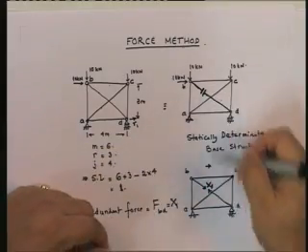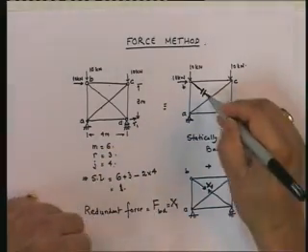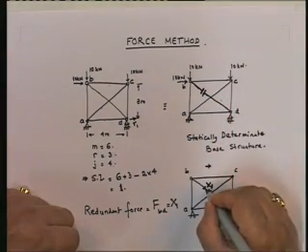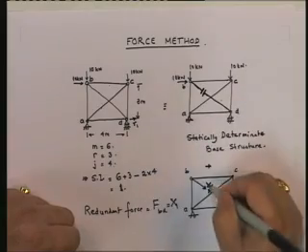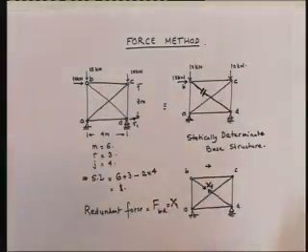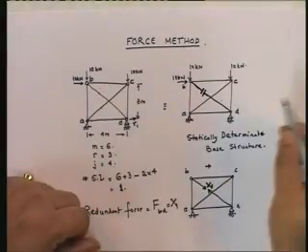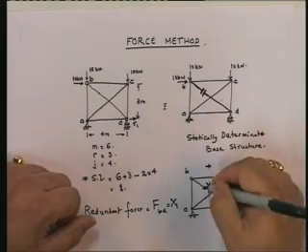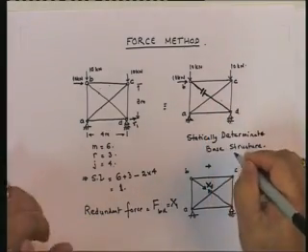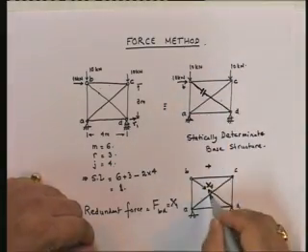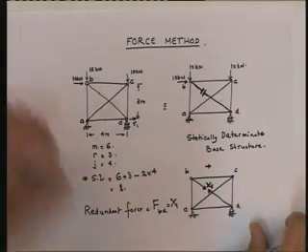Okay, so that is the independent equation. So we need to find out how much displacement I get at this point, and we need to find out how much displacement I get at this point, add the two things up, put it equal to 0, because this point cannot go anywhere, they cannot separate or overlap in the real structure, and therefore that gives us the additional equation that we are interested in. So essentially, understand that we have to find out how much this has opened by under this situation and how much this closes by under this situation. Okay, so that is the reason.